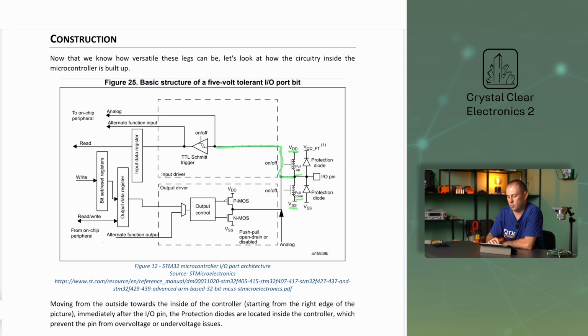There is also a third mode, the high impedance or floating mode. In this case, neither the lower nor the upper resistor is connected to the pin. In the default state, the input has an undefined value and is set to float. In this case, the external device must be able to produce both the low and high logic values independently to operate as expected. The pull-up and pull-down resistors prevent inputs from floating and the resulting accidental switching.